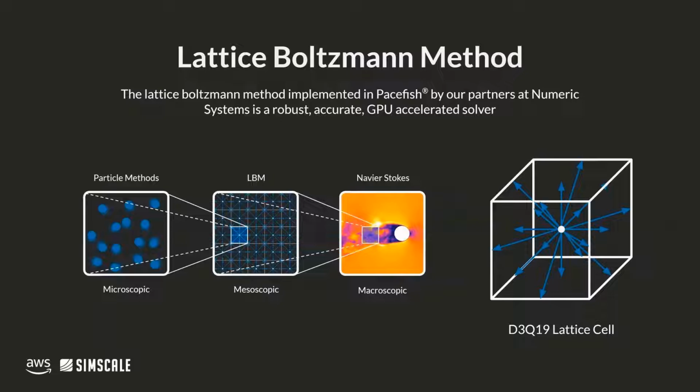We now have a problem which is discretized in 7 dimensions. The solution is set running and particle velocity probability distribution functions based on the Maxwell-Boltzmann equation are modeled at 19 places in each lattice cell. These distribution functions go through iterations of collision and streaming steps which propagate the solution through time. This is the Lattice-Boltzmann method, a modern solution for complex transient flows.